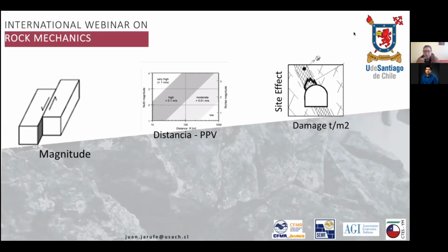So you consider the source, you consider the distance. With the distance, you can calculate the attenuation of the vibration that the seismic event causes on the rock. And then you calculate how that energy that travels through the rock mass arrives at the edge of an excavation. And then all the rock that is damaged around the excavation is excited by this energy traveling through the rock mass, and this tonnage, these chunks of material, converts to an energy demand that is usually expressed in kilojoules per square meter.